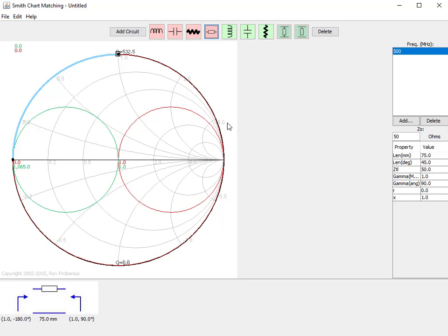But those can be adjusted using the formulas as well. Now, if we increase the length to the point where we have a quarter wavelength long, or 90 degrees, then in the reflection area, we're going to see a 180 degree shift. And since we're on the edge of the chart, you'll notice this Q value kind of dipping down. That's a rounding error. Really, the Q should remain on the edge of the chart here. It's sort of infinite. But I didn't quite tag the edge of the chart.